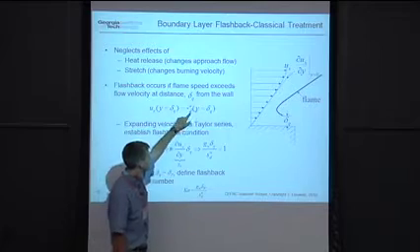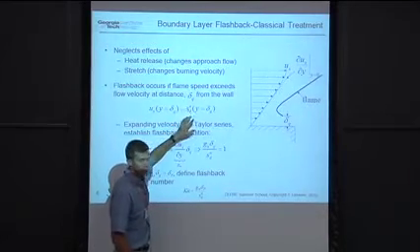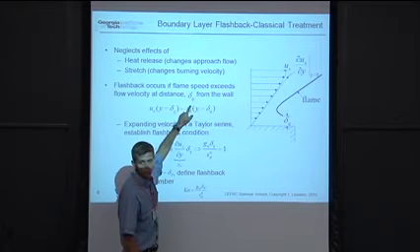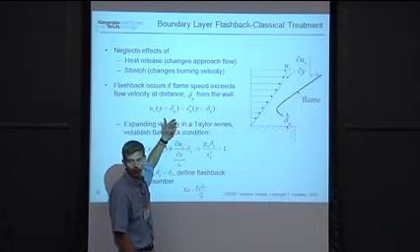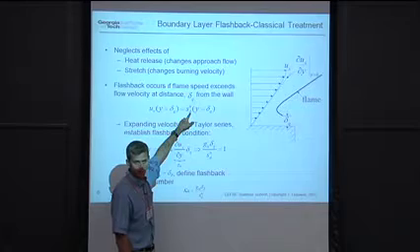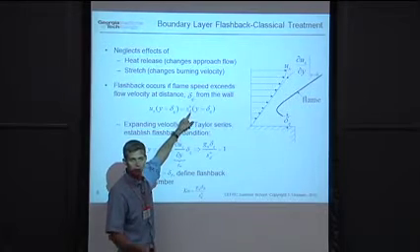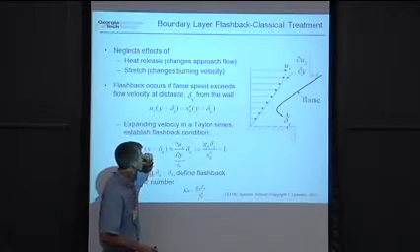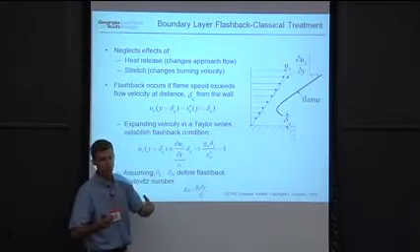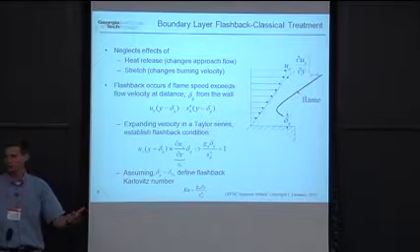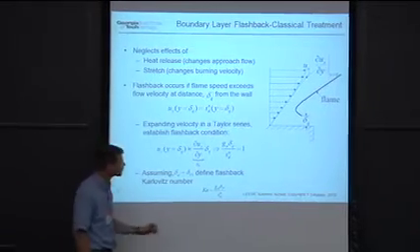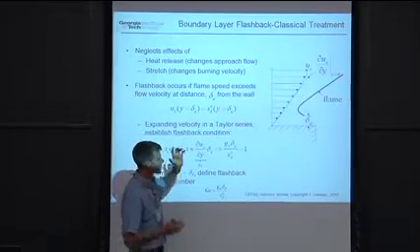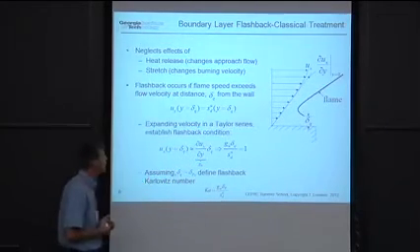And you might wonder, what's all this junk I have here? I'm pulling this straight out of my combustion textbook. S_U means the flame speed with respect to the reactants, the unburned. D means the displacement speed rather than the consumption speed. If you don't know what I'm talking about, don't worry about it. Just think of this as the flame speed. But I'm being precise because highly stretched flames have both displacement and consumption speeds, and they're different.